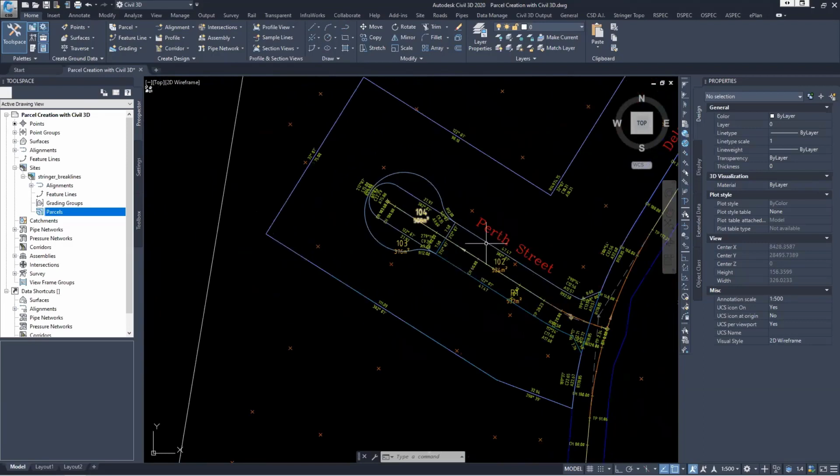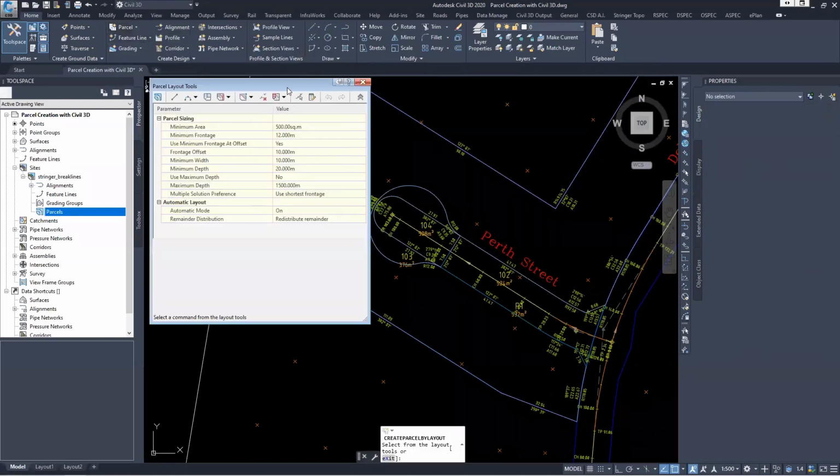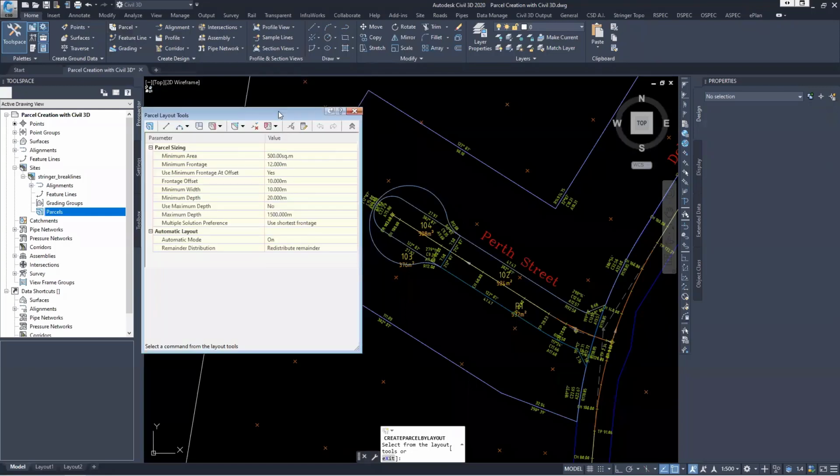Just quickly, we'll do some edits to clean this up. Just to show you how that works, this time we're actually going to open the Parcel Creation tools. Now this is where all of our edits lie and where we're able to subdivide the entirety of the lot further down the line. Now, the command we're going to use to clean this up is the delete sub-entity command. And this allows us to delete any line work that we have used to create a parcel, and it will automatically update the rest of it to represent these changes, as we will see.